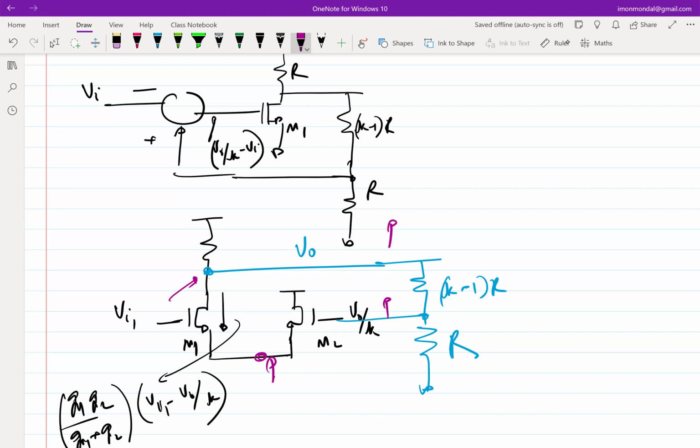You can figure it out from the current, right? This is Vx. If Vx goes up, what happens to the incremental current, in the direction that I have shown? The incremental current decreases in the direction shown. So what happens to this voltage? It goes up, right? So eventually, I had pushed this voltage up, and the loop is also trying to push the voltage up. So it's reinforcing, almost like a positive feedback loop, reinforcing a disturbance. So this loop will eventually become unstable.